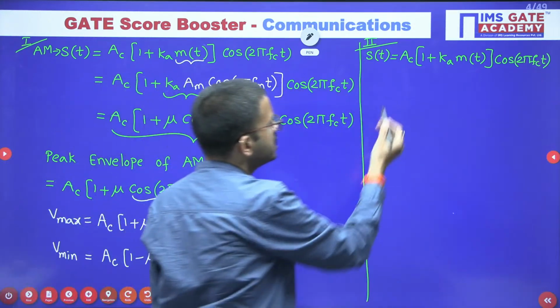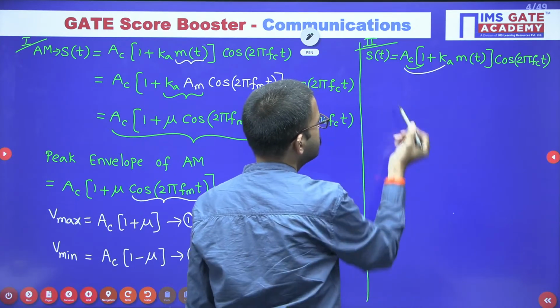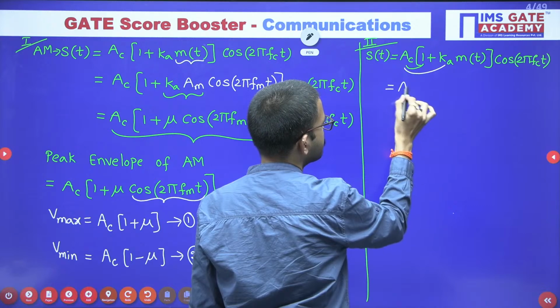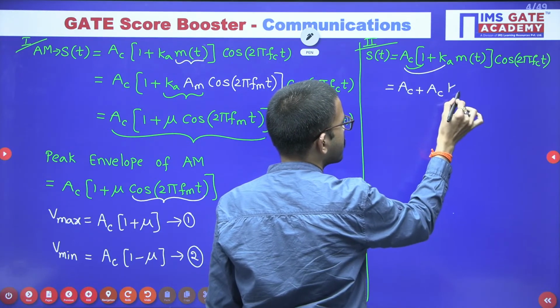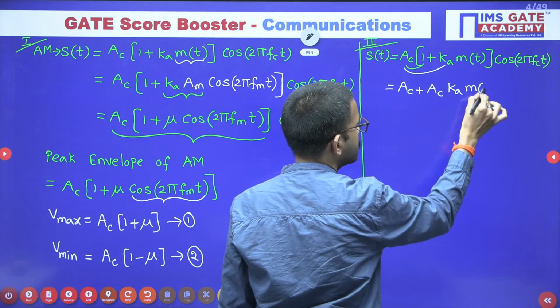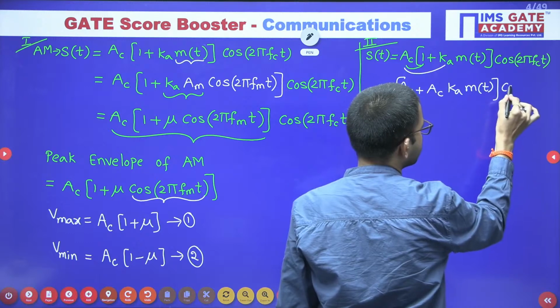Just multiply AC with both the terms. From here what you will get? AC plus AC Ka m of t into cos 2 pi f c t.